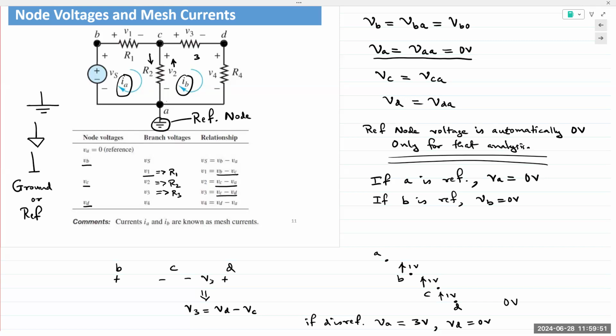It is physically impossible to have two currents present in the same circuit at the same time, both going in the opposite direction, at least in circuit analysis. When we get to semiconductors, it's a little different. There are currents flowing due to majority and minority charge carriers. That's a whole different discussion, so we won't talk about that. As far as circuit analysis goes, mesh currents are hypothetical.